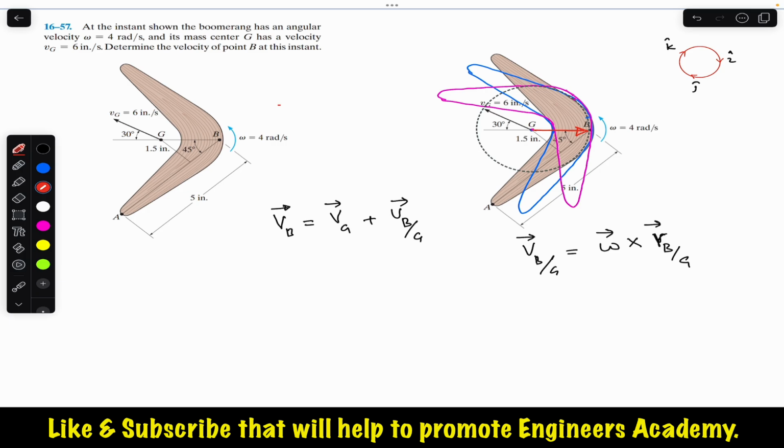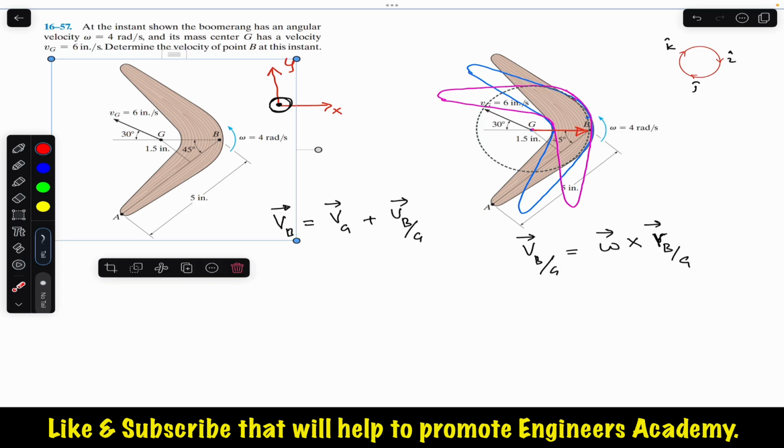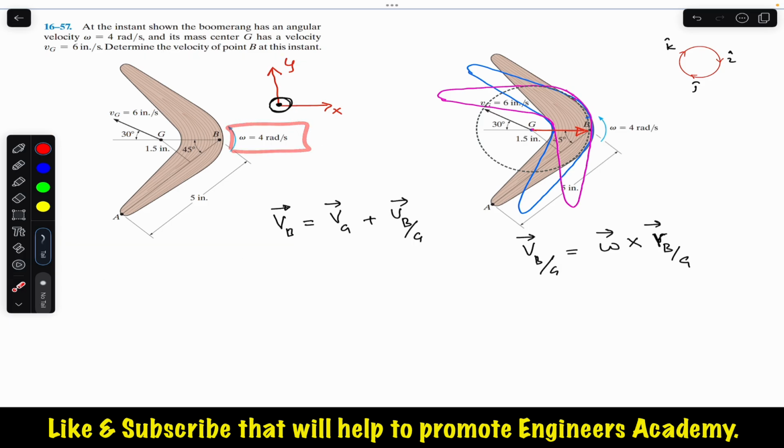If this is our positive x and this is our positive y direction, this means that omega is in the positive k direction, and this omega is 4 radian per second. So we can write that omega is plus 4 radian per second in the positive k direction, cross product with the RB relative to G. This is RB relative to G, and this is in the horizontal direction.